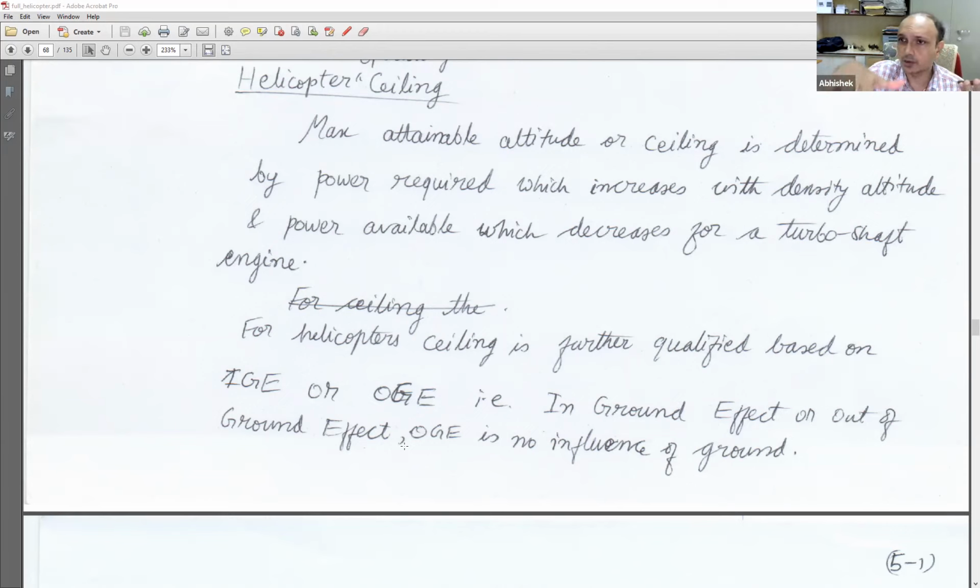In helicopters, we are always pitching and plunging. Once I give cyclic input, my blade will always be doing some sinusoidal motion. And if you remember the video we saw of a helicopter blade in forward flight, it was doing this kind of oscillatory motion and also this pitching motion.